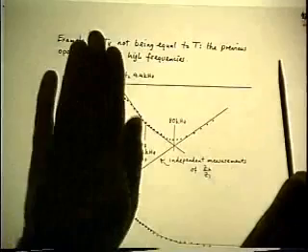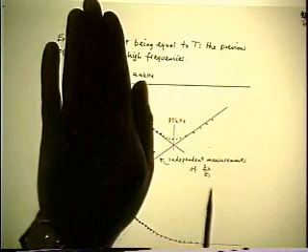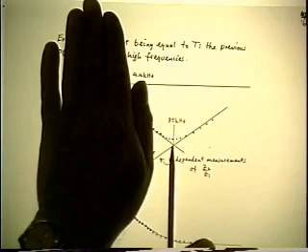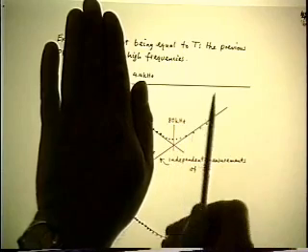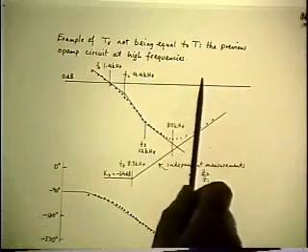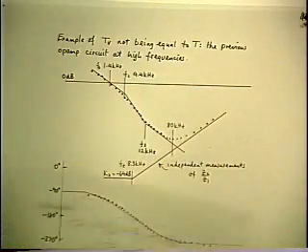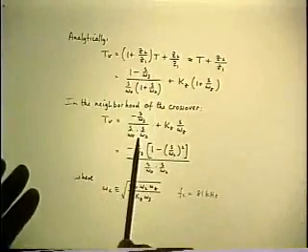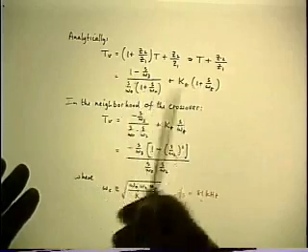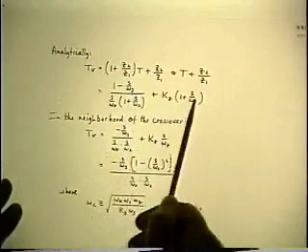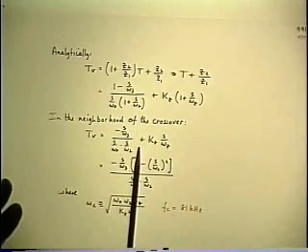So I don't care about what goes on down here. In other words, I can approximate the analytic expressions to be valid only for frequencies which are much higher than all three of those corners, which is what I've done right here. This is the same expression, except I've simply dropped the 3 ones, which is okay as long as S is much bigger than all three corner frequencies.